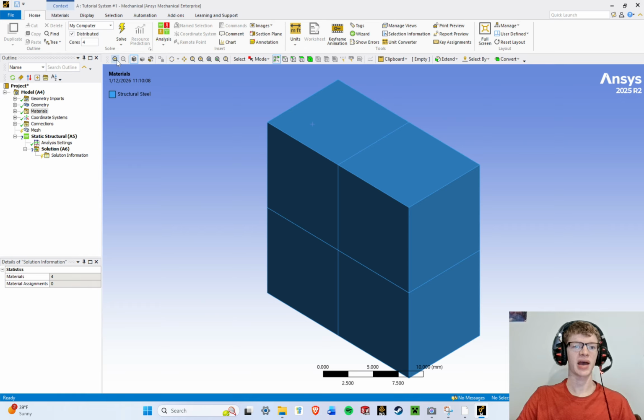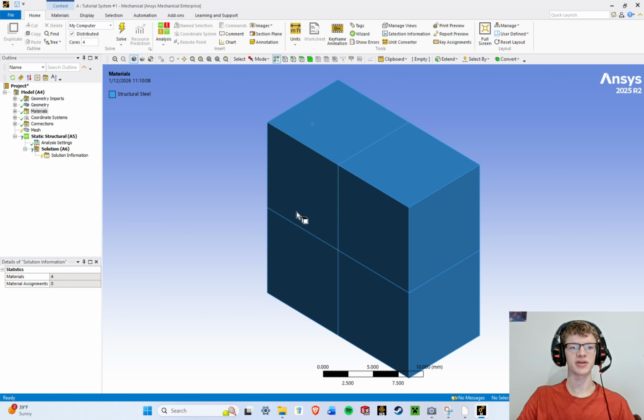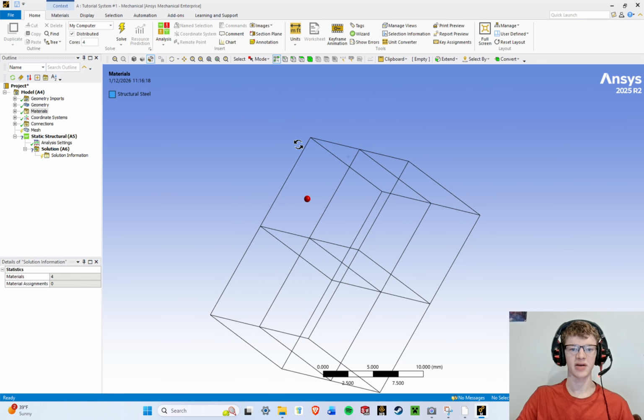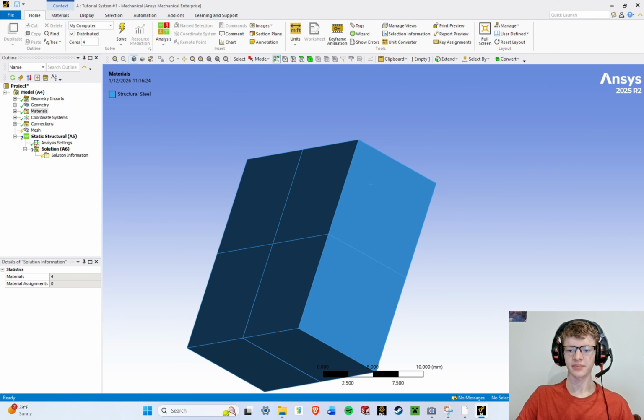And of course, we have the graphics toolbar up here at the top, which has plenty more buttons for us to use. This button will let us go back to whatever view we were at and then go forward again. It's essentially like undo, but instead of undoing, it is going to switch between views. This will let you see the geometry with shaded exterior and all of these lines, or remove the lines. This button will let you display it simply as a wireframe, which means only lines, no faces, and you can see right through it, or not.